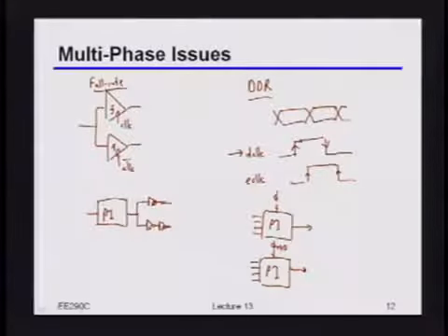The other issue is what Chintan was saying, which is, look, now I have 2 physically independent structures, and I'm kind of relying on those 2 being the same as each other, right? Because if they're not, then I'm basically going to get errors in this 90-degree spacing here. And those errors are going to translate into potentially me not being locked to the right clock position relative to my data, right?